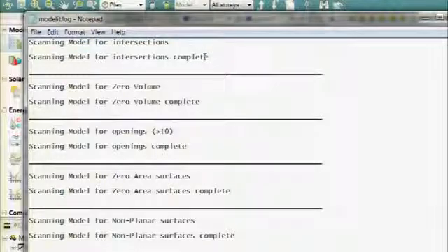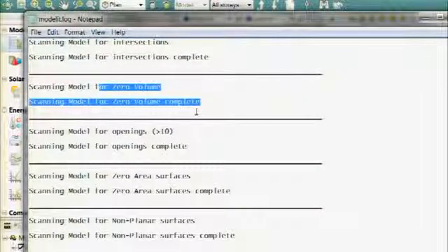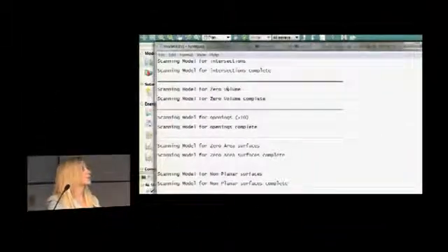For a very large Revit model, I bet there probably are. In this case, this one works out. Any zero volume spaces, so that could be a case where a space may be put outside or not bound but still exists in the Revit model. It's a big issue. Sometimes when you place a room in a Revit model, it will say, this room has been deleted from view, but it has not been deleted from the project. You've probably seen one of these errors come up that you end up closing because there are so many. But it could be a zero volume room that you have.